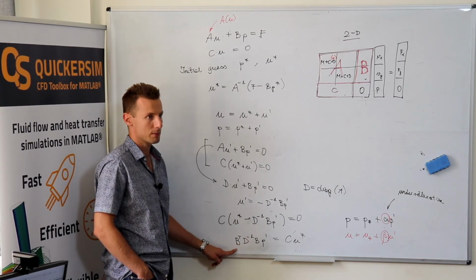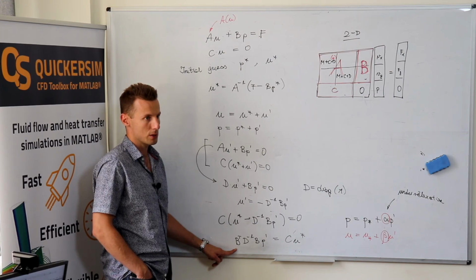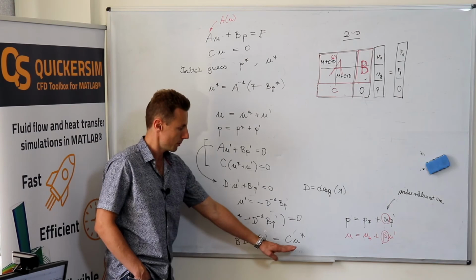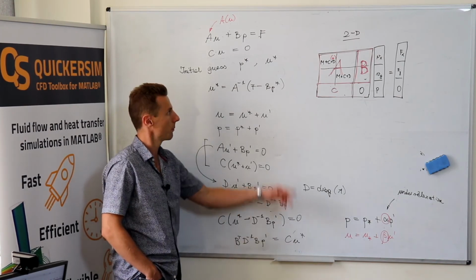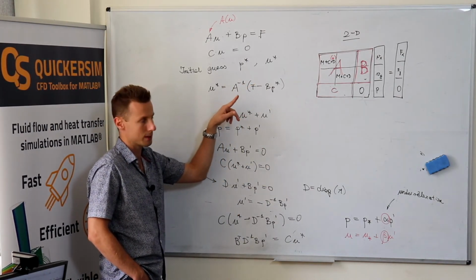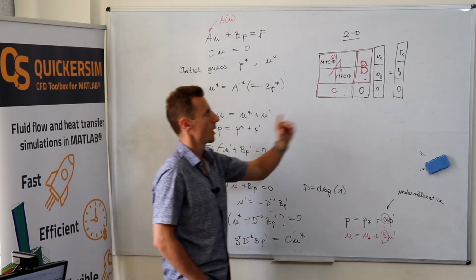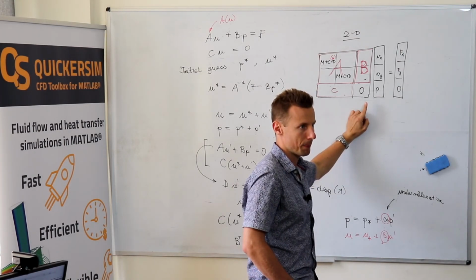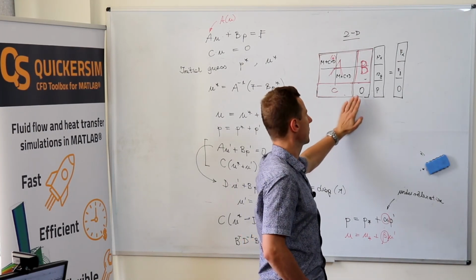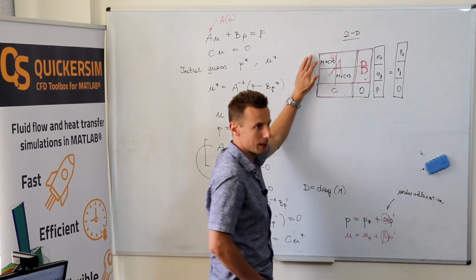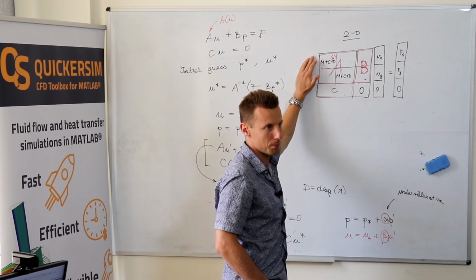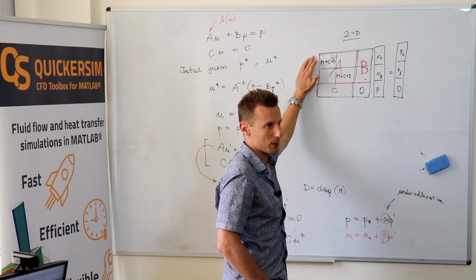It's a symmetric positive definite matrix, which is extremely similar to having the Poisson equation for pressure, but we have derived the right-hand side from this whole substitution, etc. Right now, I don't know if it's possible to replace the, I mean, if you generate the pressure Poisson equation for the unsteady Navier-Stokes equation, then it's probably possible because it's how you do the splitting in such schemes that exploit pressure Poisson equation.